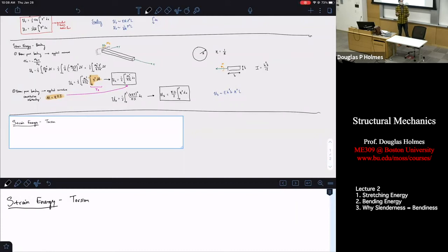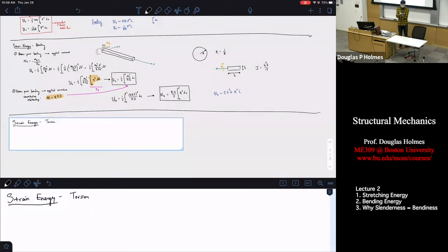And this may or may not have been clear to you when you took mechanics of materials. But let's see if we can look at this really quickly. The stress in bending an object. And I'm just going to put it like an approximate or scaling term here, because depending on which axis you're using and which direction you're going in, it could be a positive or a negative sign. But for right now, the sign doesn't matter. I just want to show you that the form of the equations are the same. So I'm going to say that the stress in bending is equal to the moment times y over I.